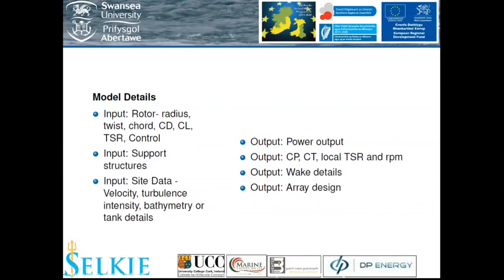The input details for the tool are: for the rotor, you have to input your twist, chord, lift and drag, TSR, and control, whether you want to analyze stall or pitch regulated tidal stream turbines. You can include your support structure and details about your tank dimensions or the bathymetry, so velocity, turbulence details, and the geometry of the bathymetry itself.